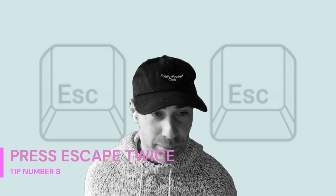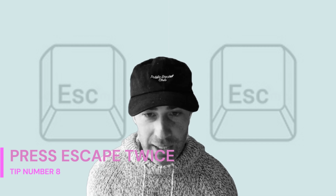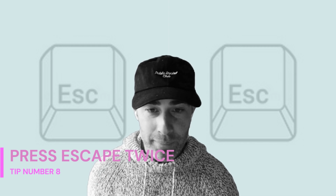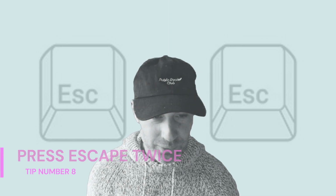Tip number 8, press Escape twice to exit creation mode. A lot of new users get confused when adding new elements because they're stuck in creation mode. Revit wants you to create many elements unless you tell it to stop. So hit Escape twice to get back to normal and moving around Revit.